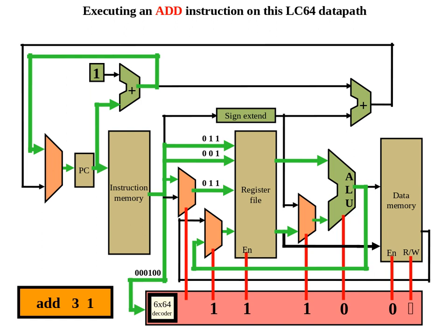So that mux says we're going to read from the ALU, forward it to the register file. This mux, which should be a 0 from our decoder, signifies that we want to forward this value, which is where we're writing to. The reason for that is other instructions may have a different write value. So we're going to forward 3 as where we're writing. We're going to forward the data from the ALU to the register file, and then that will complete add.